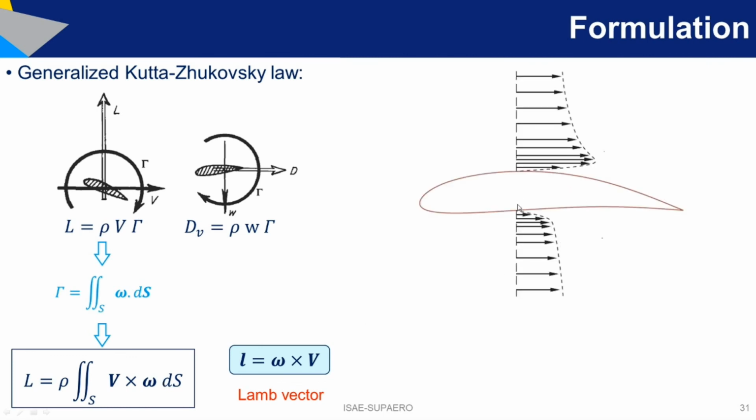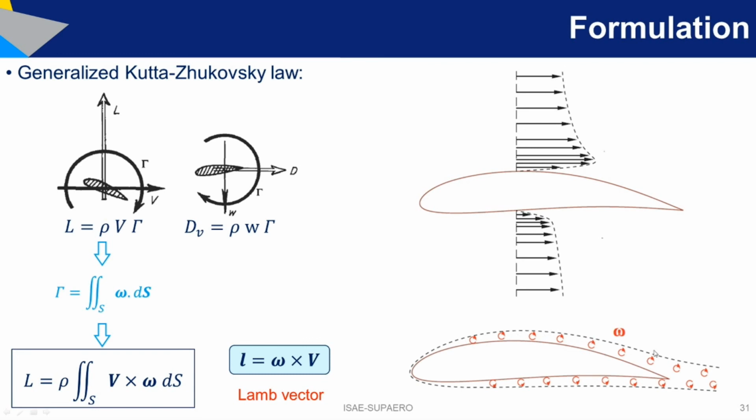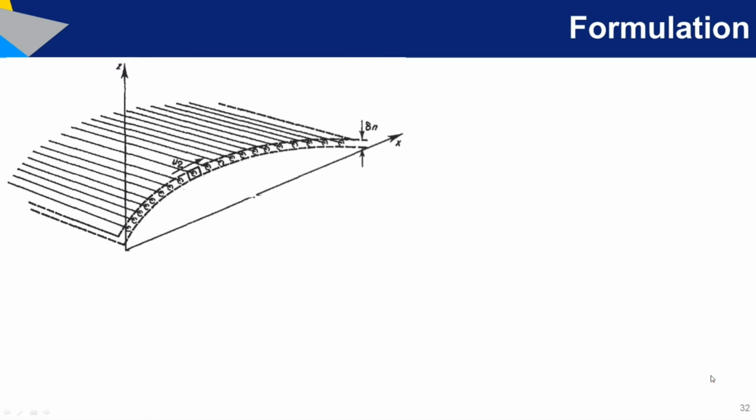First of all, as I mentioned, vorticity is a wake-restricted parameter because vorticity is only inside the viscous region, inside the boundary layer or inside the wake. So based on that idea, let's consider, for example, the upper surface of an airfoil. At a given point, you have a certain amount of vorticity, shown here with this arrow, and also represented by this arrow here.